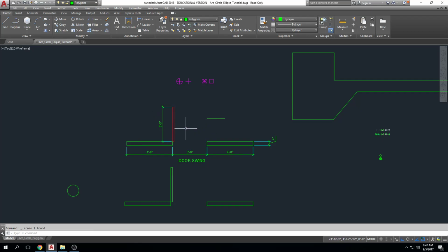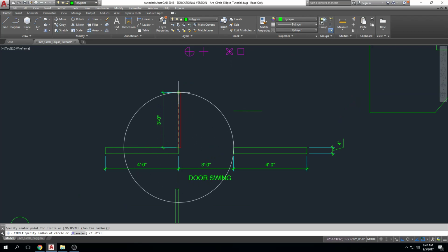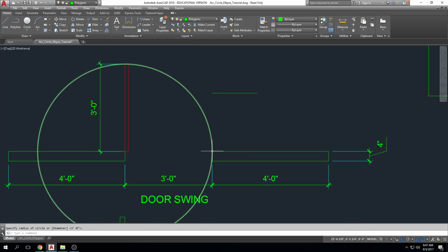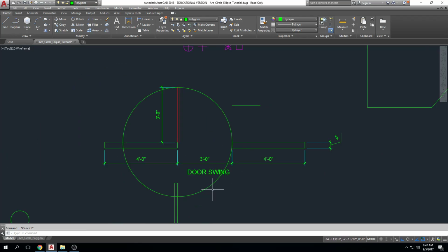So when I created that door swing, I clicked on my center radius. You could, if you wanted to choose one, center radius, click, click, and it defined that circle. And when I create doors, this is the way that I do it. I trim off the excess, right? But I know that from the center to there is 36 inches, so if I use a circle to define that, it's going to be created correctly, right? And I know this has been created correctly because that door swing rests very nicely right there at the end of that 36-inch opening, okay?